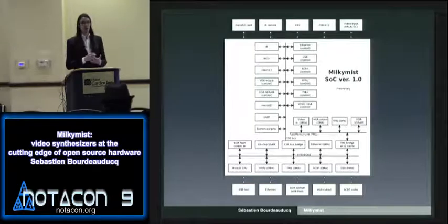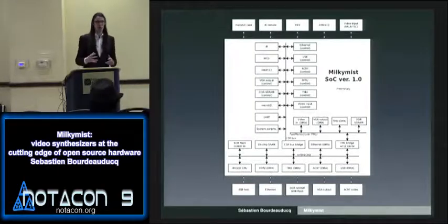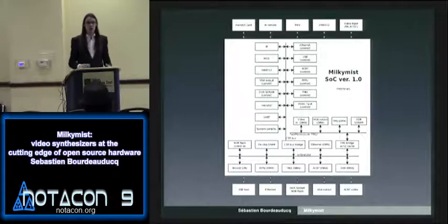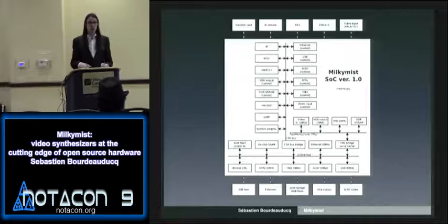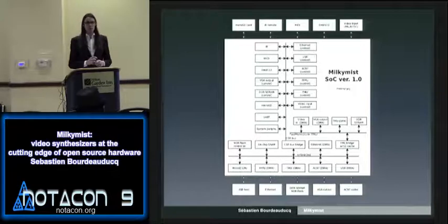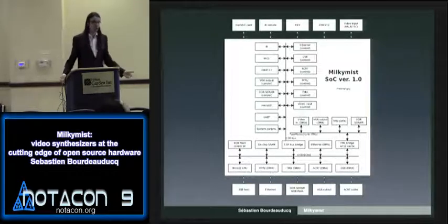In a mobile phone, you will have a CPU, which is typically an ARM device, and the CPU connects to all sorts of stuff like a UART or a GSM baseband processor, or a SIM card controller, memory, SDRAM controller. That's also what you have in boards like the Beagle board, for example. You have one chip on it, which implements all the functionality of the Beagle board. I think everyone knows about the Beagle board, right? Okay, so that's basically one chip which does everything. In this chip, you have the CPU and integrated buses and some peripherals. Basically, it's a computer on a chip.